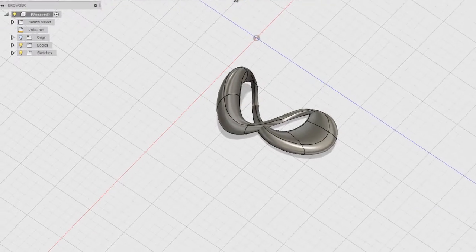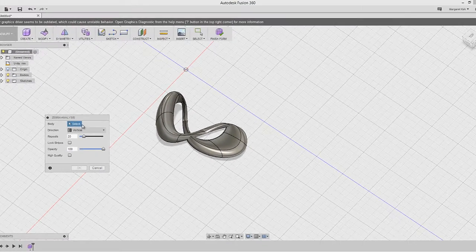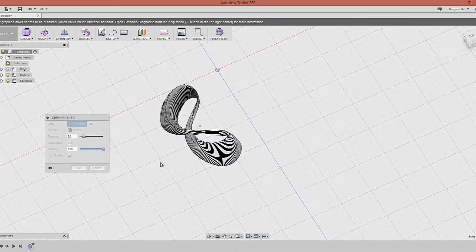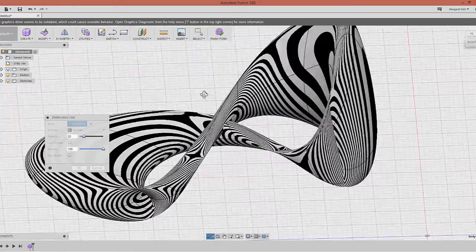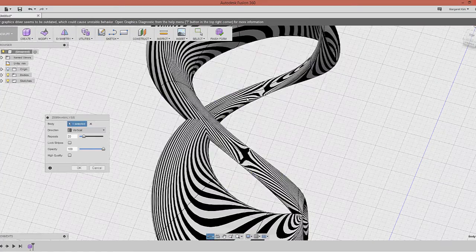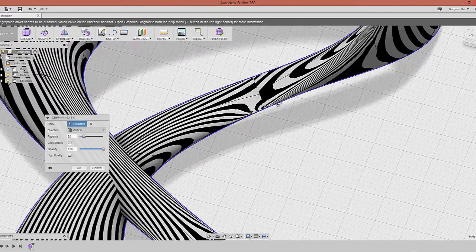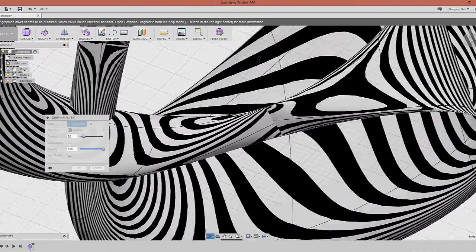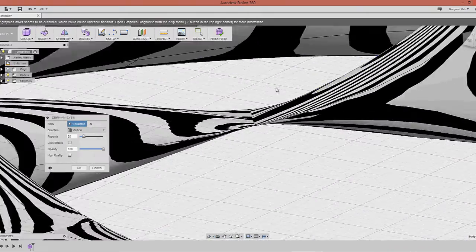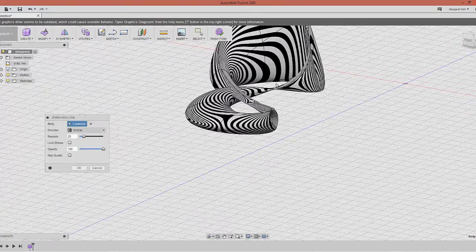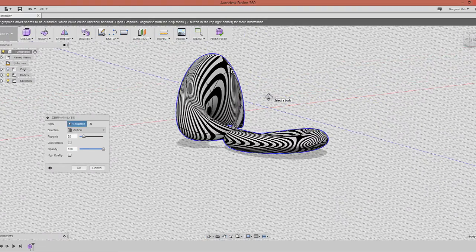And then if we go to our zebra analysis again, and I select my body, you'll see that continuity, it might not like that. It definitely won't like this. And that's where you see that continuity that's broken, right? Because we have faces that are self-intersecting each other. So this model might just give me some problems, okay? But that's good because that's a learning possibility.